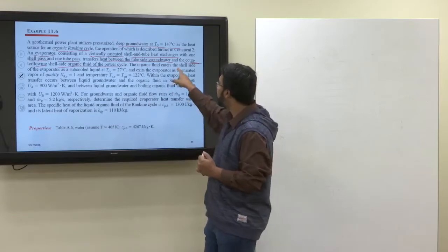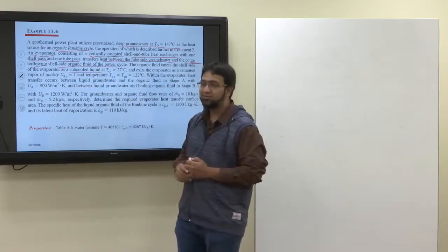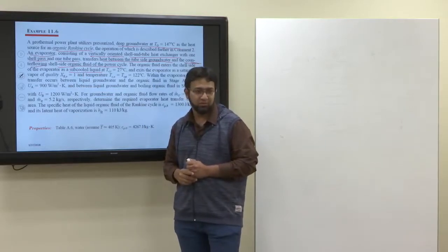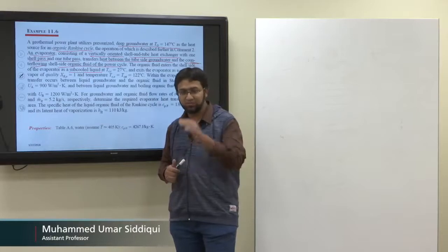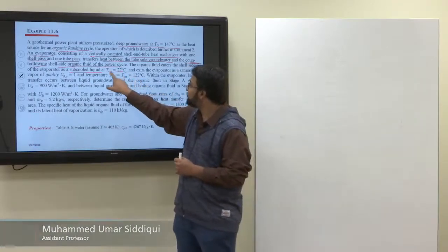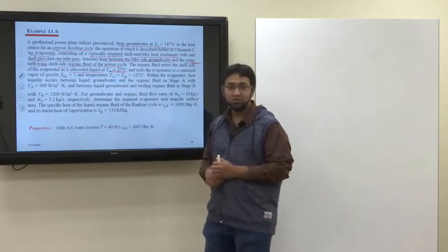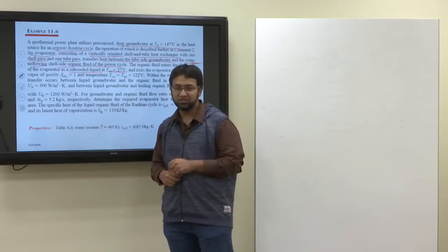The organic fluid enters the shell side of the evaporator as subcooled liquid. So it enters as subcooled liquid. That means its temperature is not the saturation temperature. Its temperature is below saturation temperature, at 27 degrees centigrade. So T cold inlet is 27 degrees centigrade.